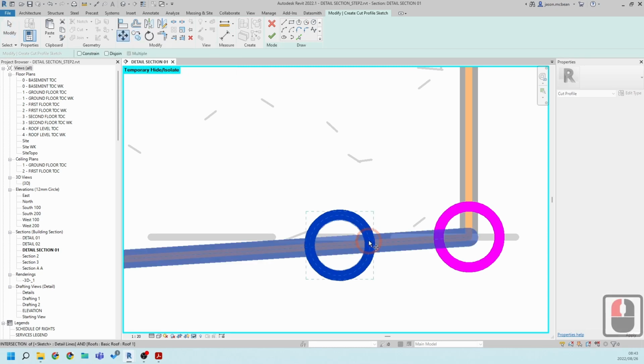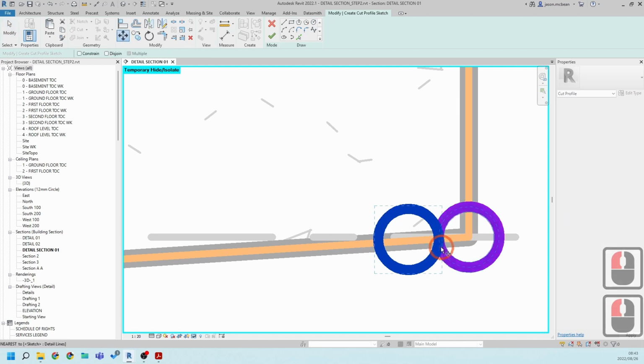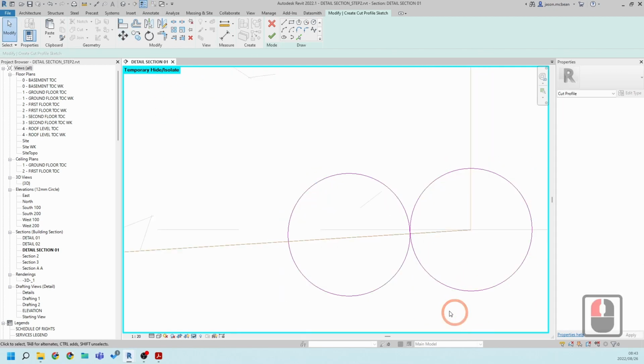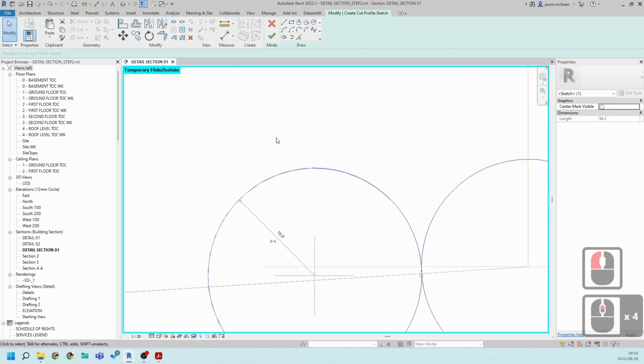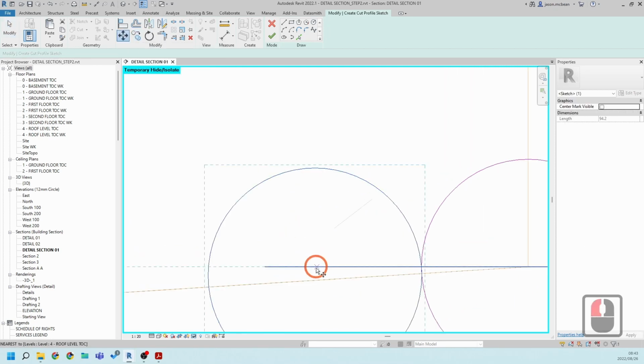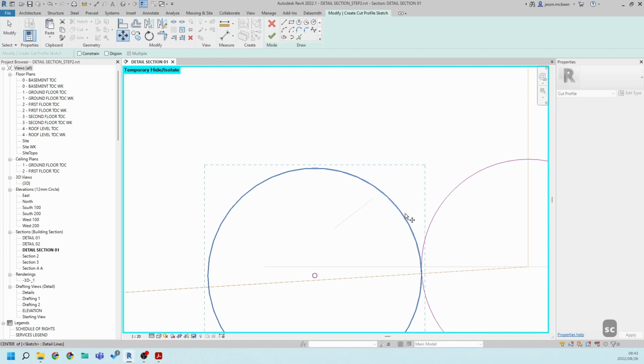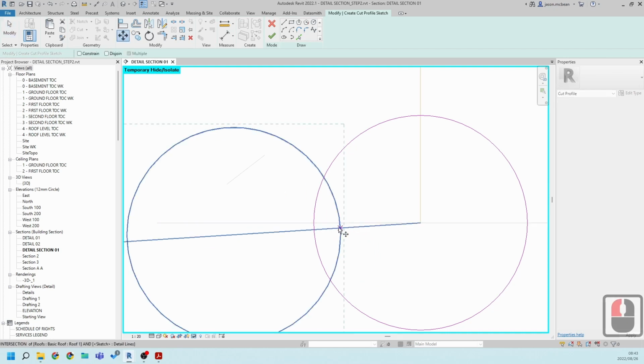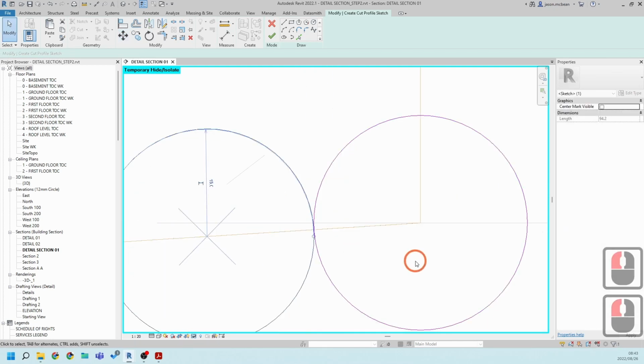So I'm going to move this information where it intersects with this circle and then move it back by 40 or 50 mil. Just remember, use your line weight tool, select this object now, move, snap center, put it on this line over here. This should have been locked on the line, so that was my mistake. Now move this from that intersection to that intersection.